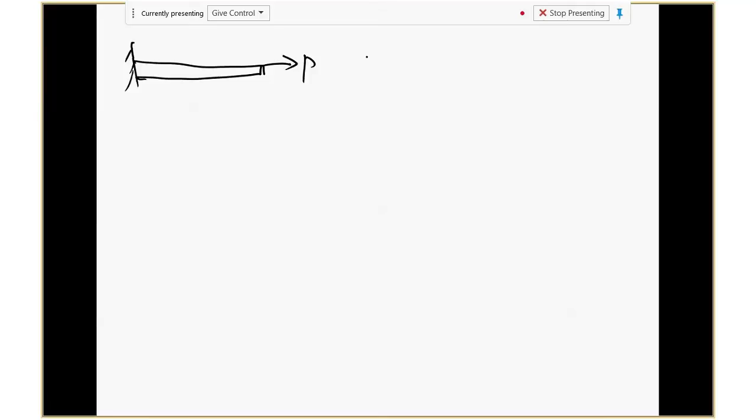Anyone remember the equation? Energy, there is a 1/2 something. P delta, always the force times the displacement, right? Why is there a half there? Because if you plot P over delta, it's like a linear spring, and the work done is this area, the triangle. So you have a half there. And the work is converted to energy. Then when it's bouncing back, the energy transfers back to work. So that's why you have a half there.